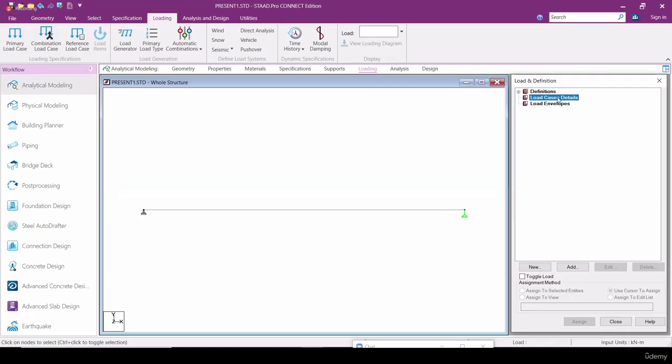In the load case details, definitions are for when you want to give any vehicle loads or seismic loads; all these things you have to define first. Also we will use this parameter in our PEBs, and I'll tell you how to use that. Because I'm doing a simply supported beam here, we are not going to define anything particular, I'm just going with load cases.